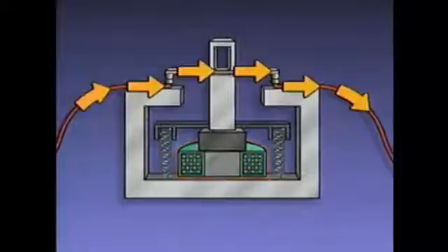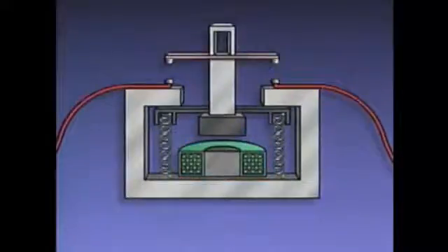When the M coil is de-energized, the electromagnetic field is removed, and the springs push the armature back to its original position, separating the two contacts.